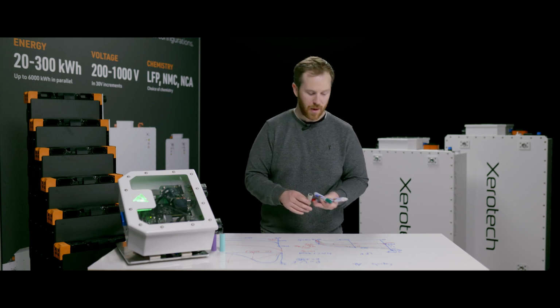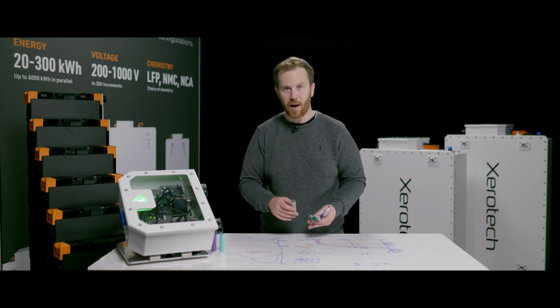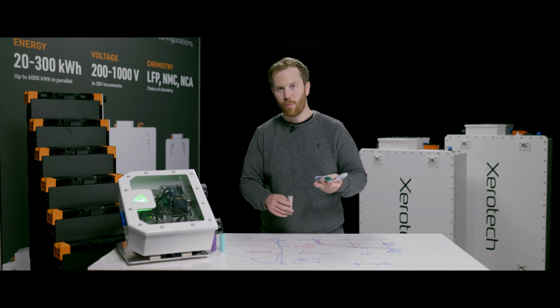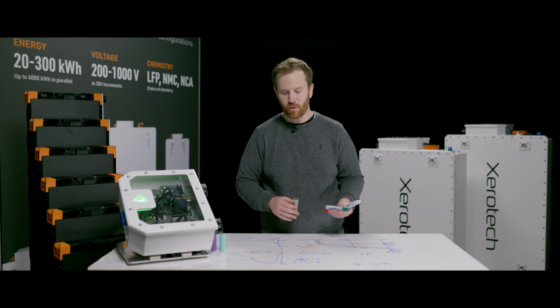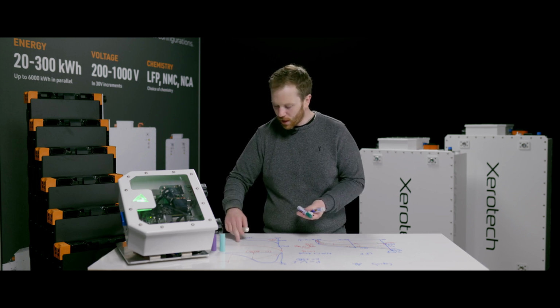The good ones are basically the ones that deliver power. As it gets hotter, the chemistry is more reactive, the ions and electrons are more mobile through the separators, so that results in a lower internal resistance, higher power output. But it also accelerates the bad chemical reactions, the ones that age the battery cell.